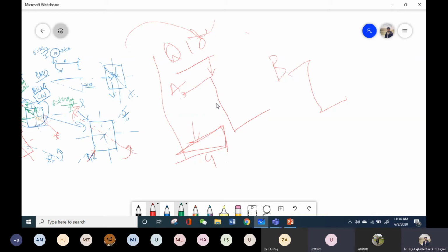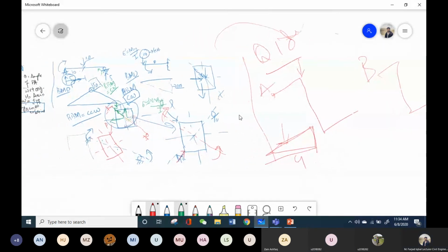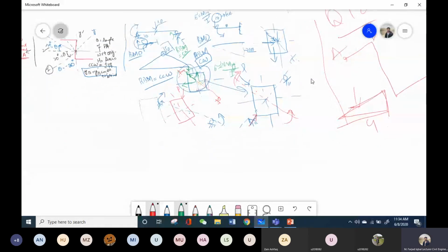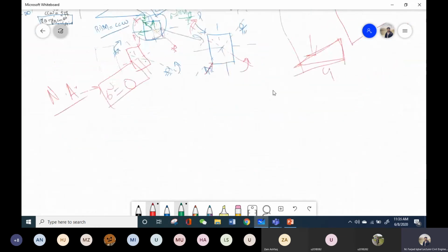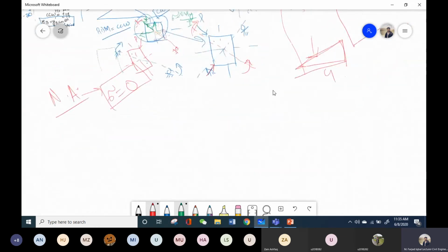Bending is about neutral axis. I would say no. Neutral axis can change. Actually, the definition of neutral axis that we have studied in this course also was that the neutral axis is the one on which the stresses are zero. Okay, it has nothing to do with bending, nothing to do with bending moments or where the load is acting. It is the axis on which the bending stresses are zero. Bending is around the axis that is perpendicular to the applied load.